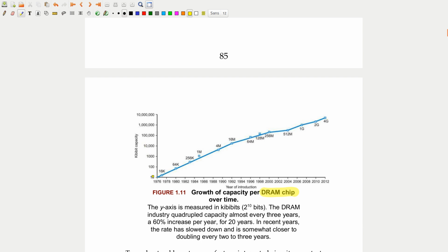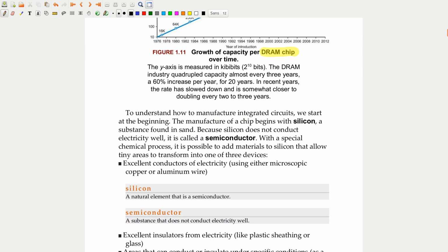So we see the same trend in scaling of DRAM capacity as we do with transistor scaling. And so it's very easy to see why. Because in essence, what is DRAM? DRAM is only a single capacitor and a single transistor. So if we halve the size of all of the transistors, it makes sense that our capacity per unit area is going to double. So that makes sense to us.